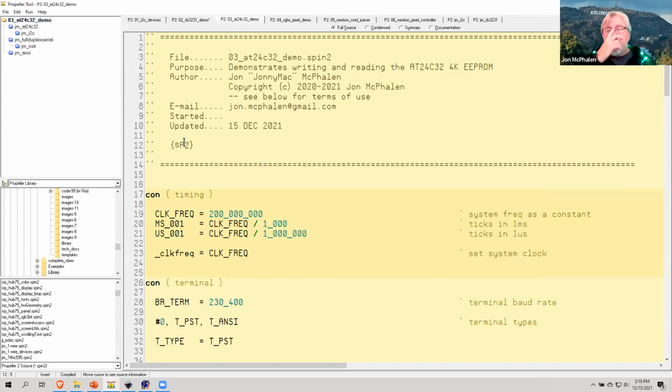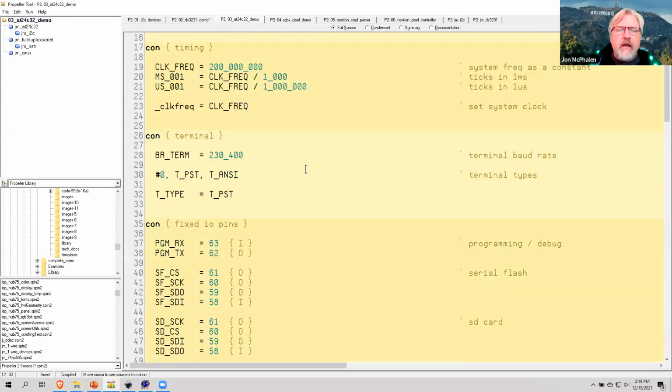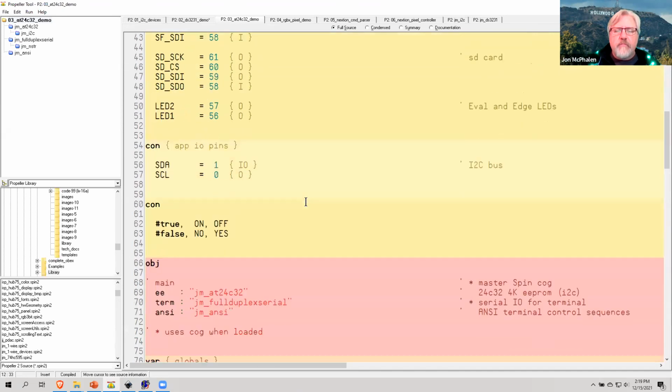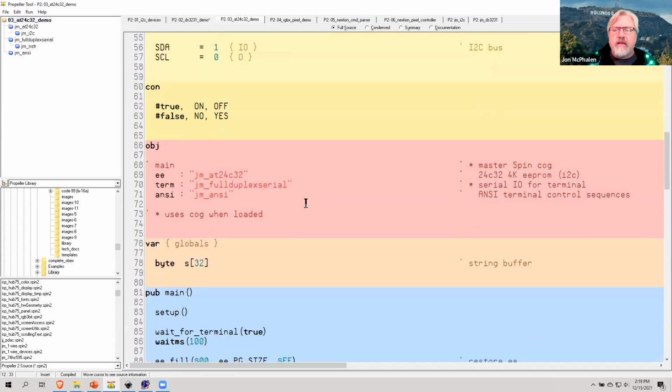Okay, EEPROMs are super easy. The nice thing about P1 projects is that, in fact, my friend John Huffman has lots of products that use the P1, and in the P1, it uses 32K of EEPROM, but you would always install a 64K EEPROM because that way you could put non-volatile data in the upper 32K, and even if you had to reload the program, that data was protected. So again, we don't quite have that yet, or it's not as easy yet to do that kind of stuff with the P2.